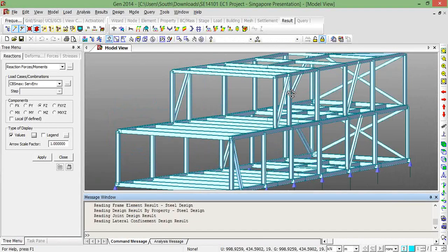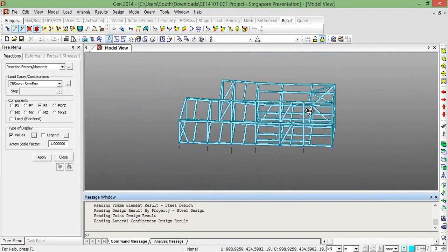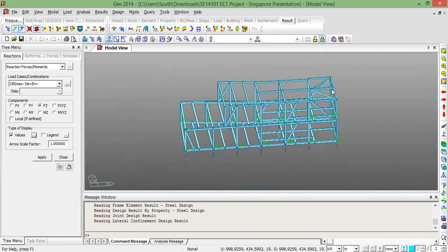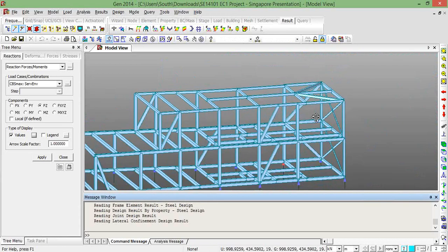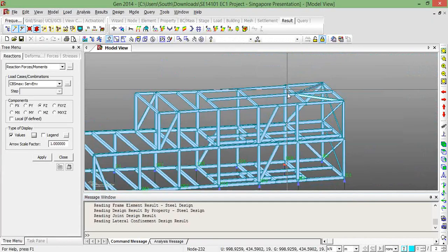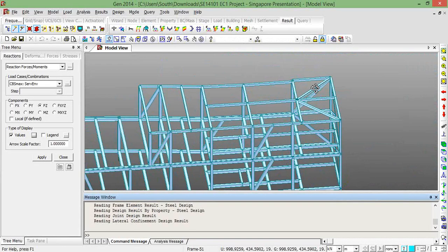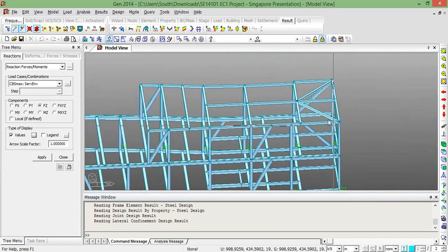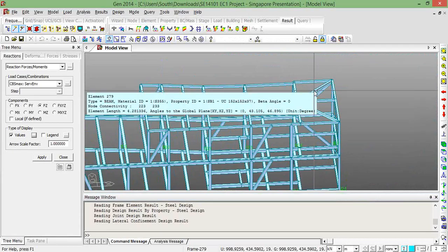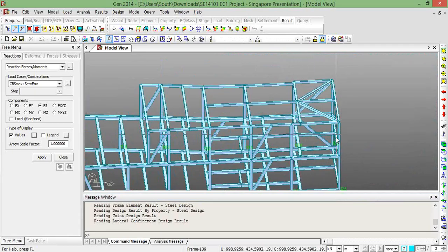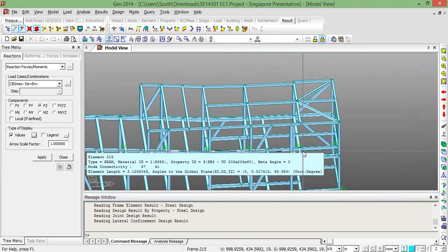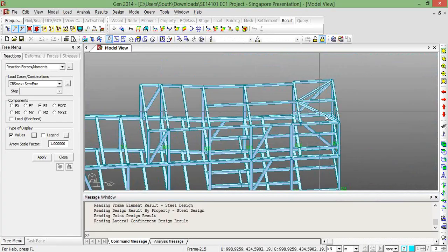So what we did here to make up for that and bring in some stiffness, particularly at the top where we would experience the most amount of deflection from the base, is by bringing in these cross beams here. So when the structure would move, this beam would then be in tension and bring some stiffness back into this frame. And if the wind load was applied in the opposite direction, the same thing would happen here with this cross beam.